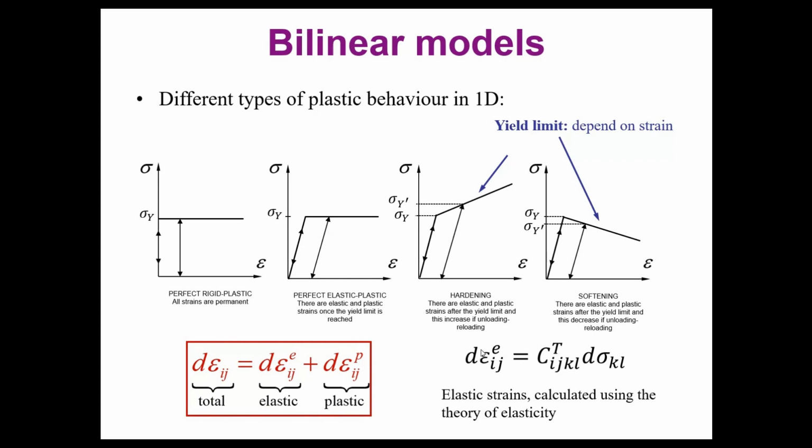the same equation for the elastic regime. In this case, I have put the relationship between strains and stresses as differentials, just in order to be able to capture any non-linearity, and because when we reach the plastic regime, we are going to be forced to work in increments, because we need to capture the change in behavior of the yield strength, and we need to capture any unloading or reloading process that the structure will be subjected to,